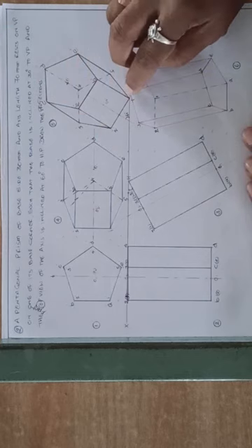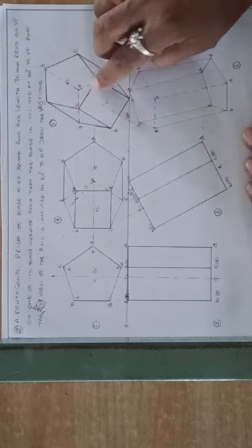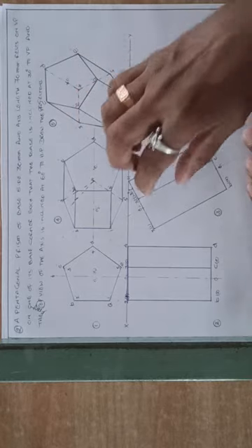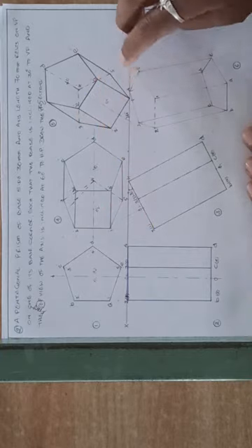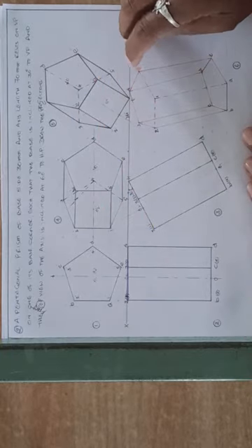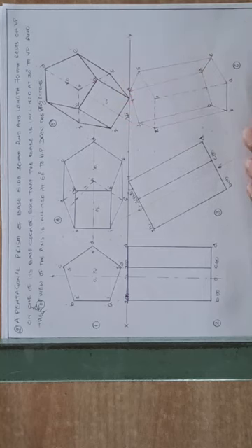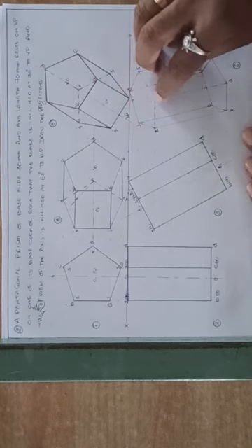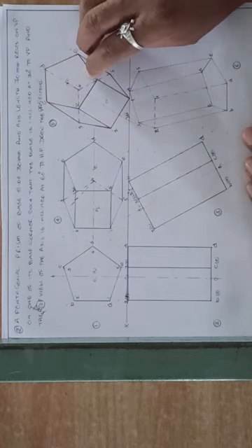So now I am projecting 1 dash downwards, 2 dash downwards, 3 dash downwards, 4 downwards, 5 downwards. Similarly, horizontal projections from 1, 2, 3, 4, 5. Now mark the points 1, 2, 3, 4, 5. Just mark the points with thin lines. Don't join with thick lines, just thin lines. Now coming to the face, the top face. Again draw the projections downwards.